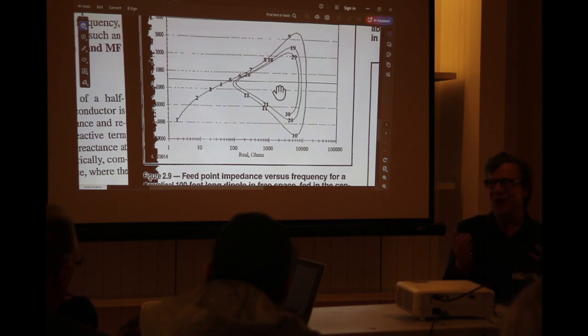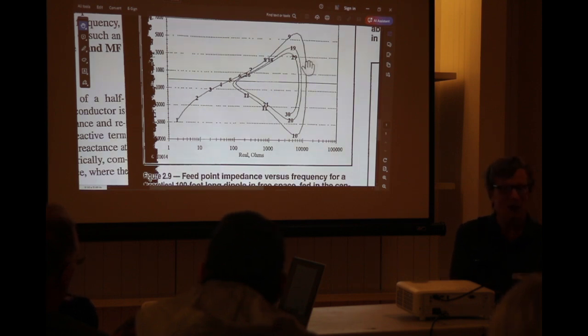So you've already narrowed your possibilities of frequency range by virtue of the fact that we have so much that depends on the height and everything else. But also, the transformer does nothing to address this sudden change of reactance, right? Transformer will give you the right resistance, but all your reactances are transferred right through that transformer. So if you got a touchy antenna, it doesn't matter how well you match the thing, it's going to have a dramatic change of reactance here.